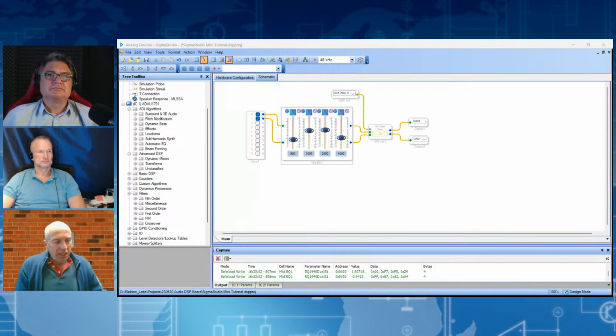It's an interesting point actually for this board, because by default the DSP works on its own. It does its own thing, and if you want to use it as an I2S master, I2S is also a master-slave protocol, then the ESP must be slave.